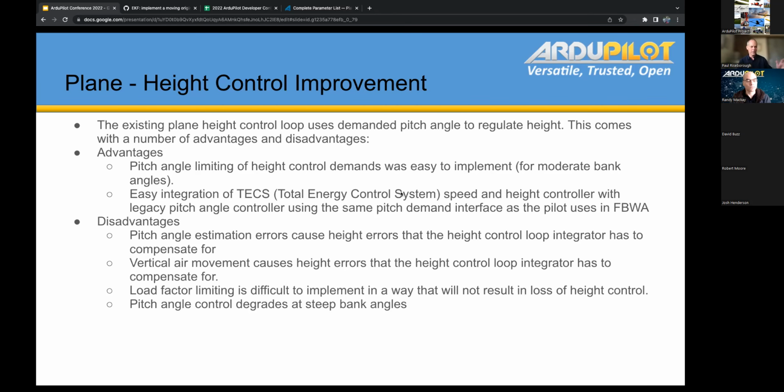And I think there was a question that came up, I wasn't there at the call: what happens if the EKF is trying to correct its origin for the difference between the pressure altitude and the GPS altitude at the same time? And the answer is, by default, we don't do it, but there is a parameter option that enables you to, it's called EK3_OGN_HGT_MASK. I'll put it in the chat window.